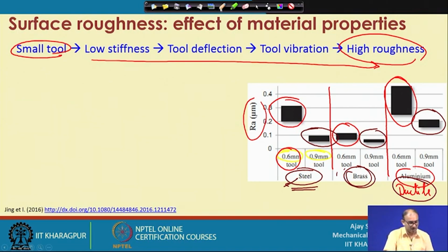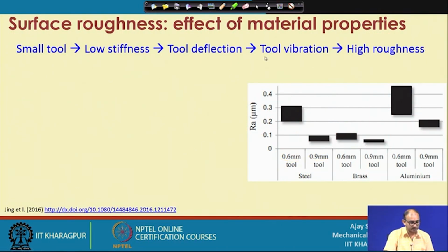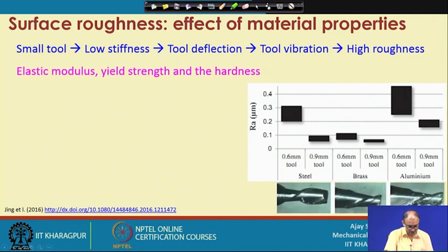So, this is the diagram that it is showing. This is the chip. Now if you see the condition of the cutting tool, when you cut a steel material, you can see that there is no chip clogging on the flute of this cutting tool. But if you see aluminum, there are many chips which actually stick to the surface, and these chips are creating problems. Now if you use this cutter, the chip will not get the flow or the passage through which it will come out of the pocket which is going to be cut.